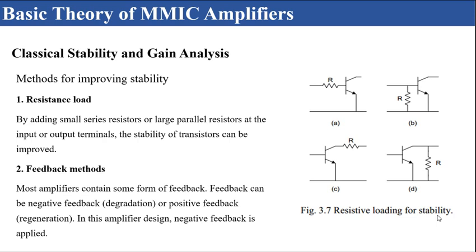First is resistance loading. By adding small series resistors or large parallel resistors at the input or output terminal, the stability of transistors can be improved. Adding resistors creates a trade-off between noise and gain. Therefore, if adding resistors, the application specification must also be considered.